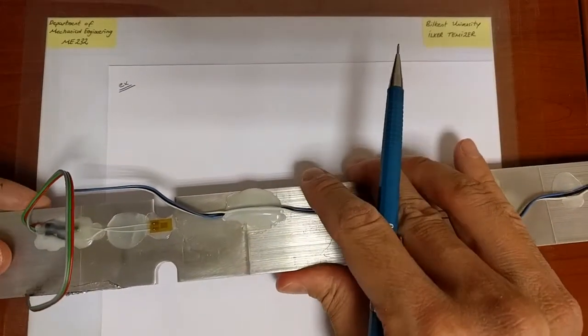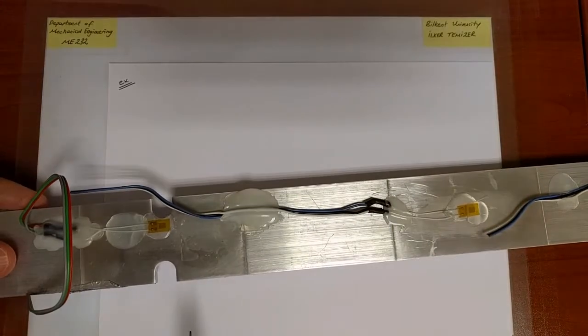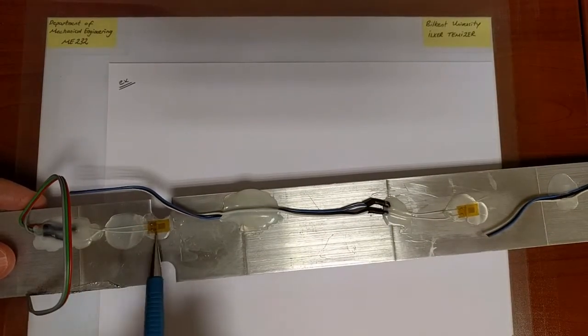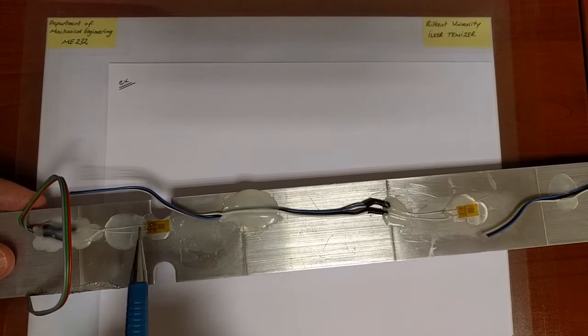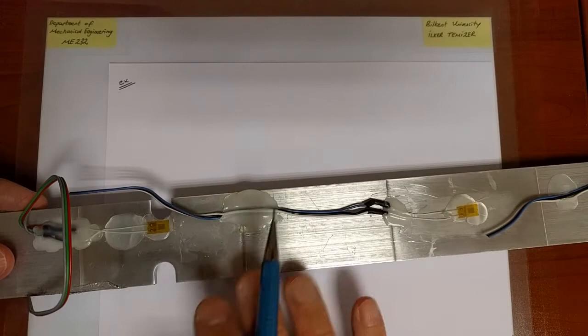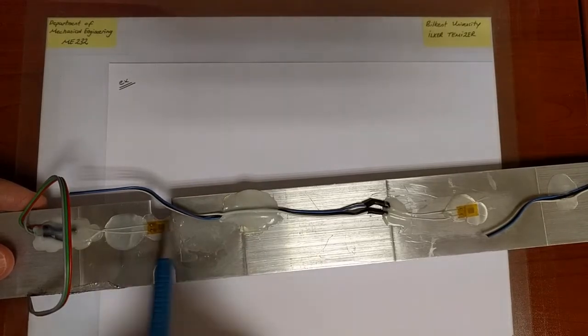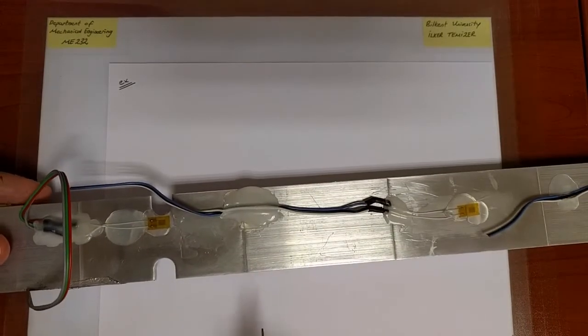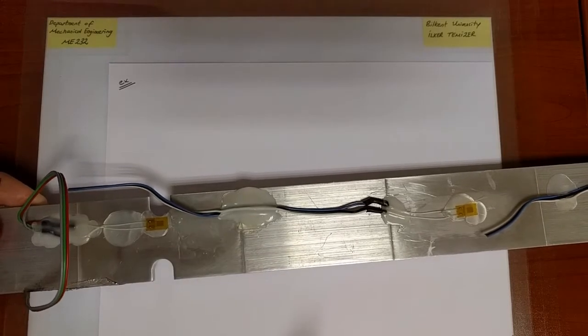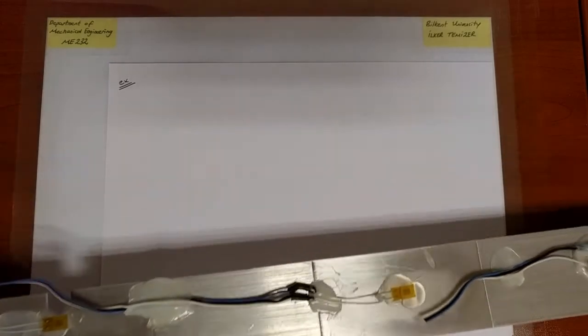This thing will be loaded within the plane of this beam, but not in a direction that's perpendicular to it. So no shear or normal stress is associated with that direction. So it's a state of plane stress, and the plane that we're talking about is the plane of this beam. Okay, so now having motivated our idea, we will go ahead with an example.